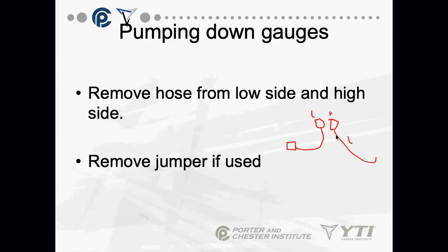If I open a valve to allow the liquid refrigerant out of the high side gauge into the low side and suck into the system on the suction line, all I'm left with in these gauges is vapor. And it's actually a pretty small quantity of vapor. Now I can take the low side hose off, and all I have left in these hoses is vapor. I'm minimizing the loss of refrigerant. I know some people have to have questions on this.